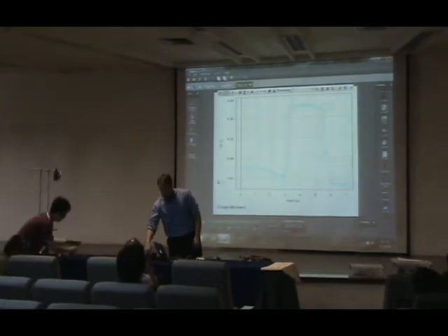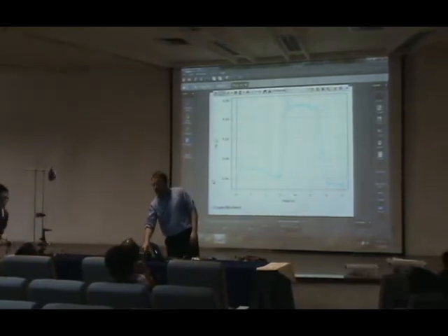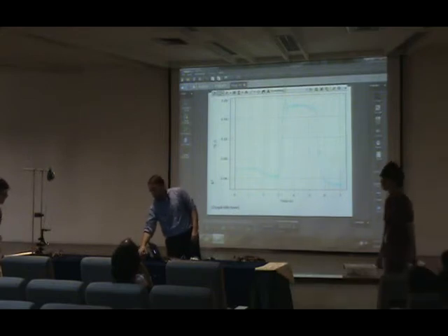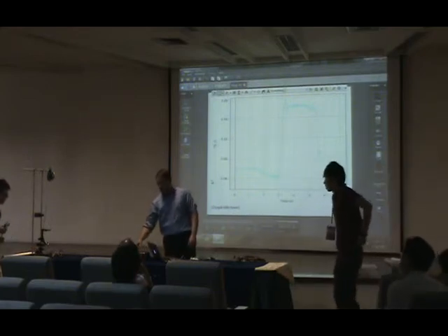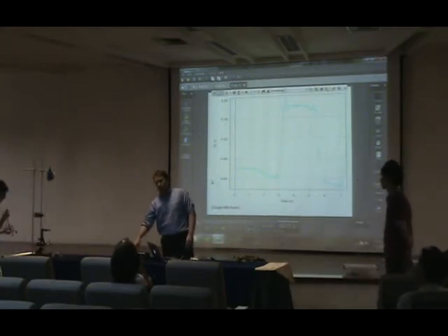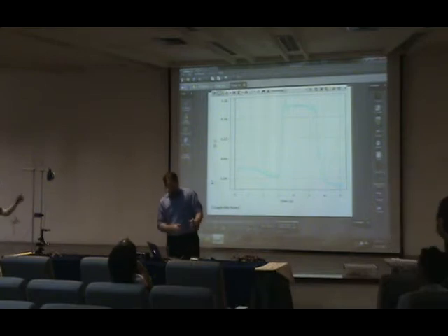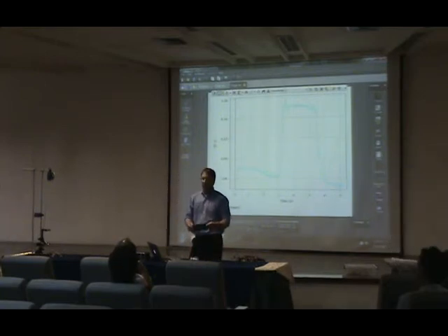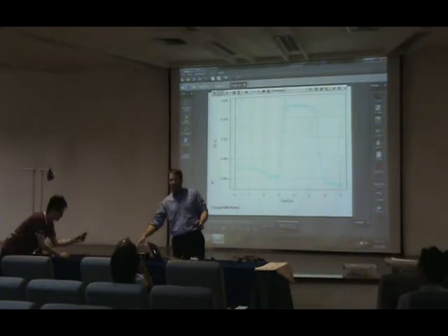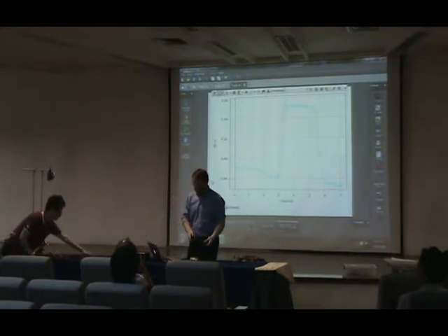One is it has 3 signal generators. It has a high power 15 watt power amplifier, and it has 2 high-speed signal generators that each go up to 500 kilohertz. Now 500 kilohertz is only important if you have a box that can measure and keep up with it. This box measures at 10 megahertz. So we're going to be looking at the same components that you would typically use in other circuits, so I don't need any fancy components here because I have a sampling rate that's able to keep up with the LRC circuit phases that your typical components will do.